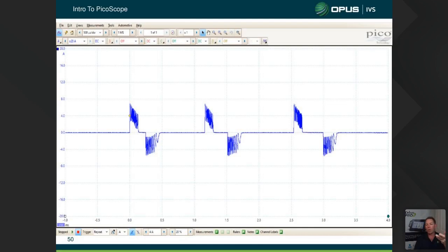So we open it, we hold it open for, 4 milliseconds, or actually, no, this is a diesel, so a lot less. We could measure this. We hold it open for a certain amount of time, and then we reverse the current flow to close it.